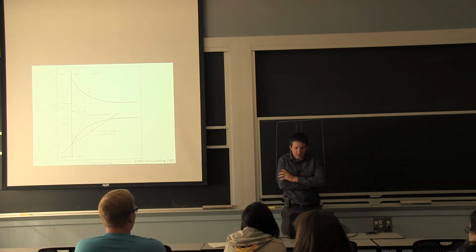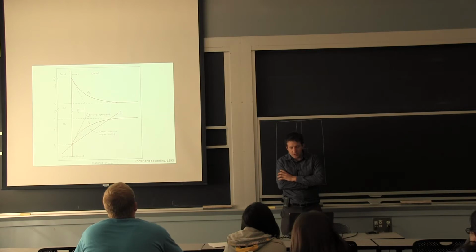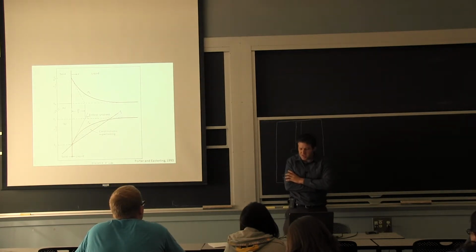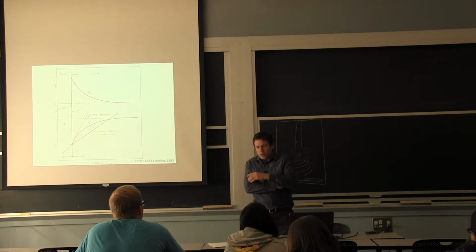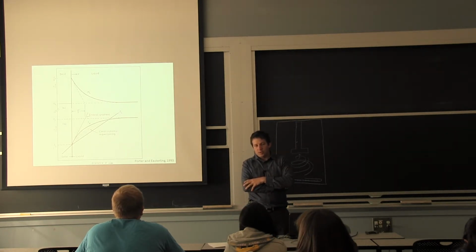It's not the easiest, but it's the most complete explanation, I would say, about why we have an unstable solidification front. So they call it constitutional supercooling. Supercooling just means that you are at a temperature below your fusion temperature for that composition.